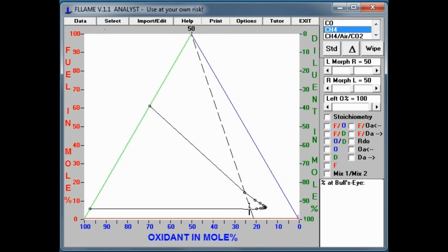The right axis is between the pure nitrogen and pure methane points, and the connecting line does not pass through the fire region, so nitrogen is a potentially safe purging fluid.